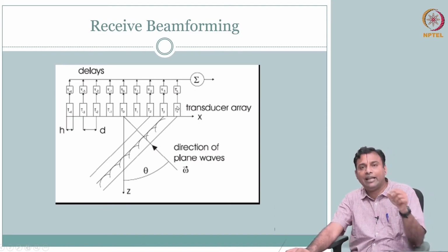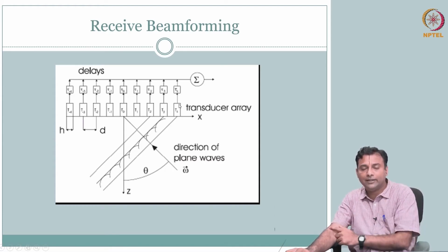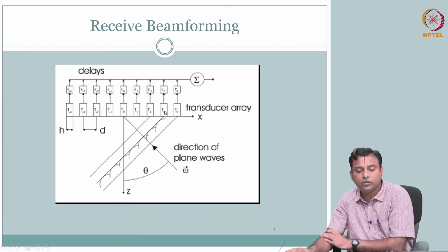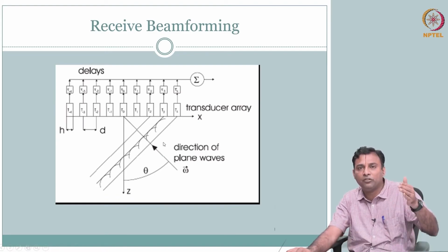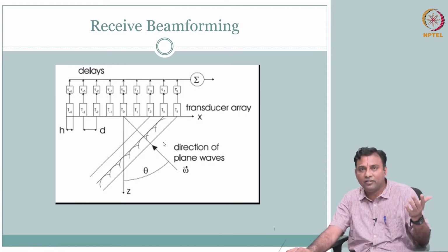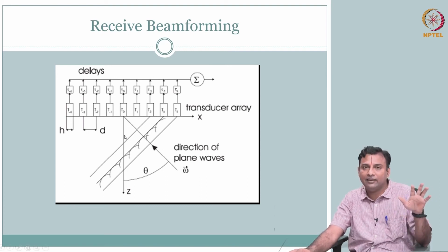Each channel will have a corresponding analog to digital converter. So, you have this trace, transducer 1 has one signal, transducer 2, so each one is receiving the signal. Straightforward, apply the delay: the earlier one that you got, you have to delay more until you get the last one, right. It is the same profile that you got for transmit, inverse of that. Whichever was delayed most there will have the least delay here. You can get your receive data.